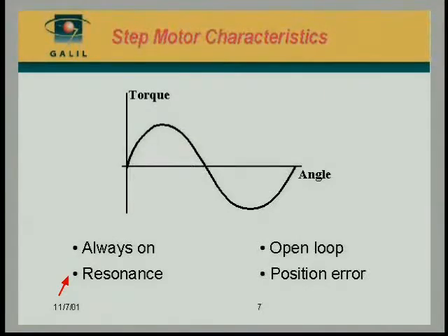This is something that, as I mentioned, is very nonlinear, but could be changed by changing the drive characteristics, changing the voltage, modifying the current loop, and so on, could solve that problem. Nevertheless, that's something one has to be aware of when dealing with stepper motors.